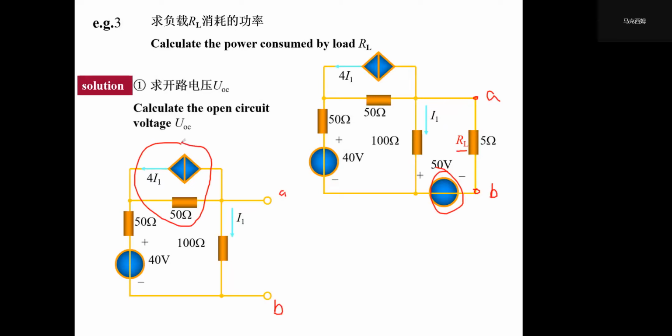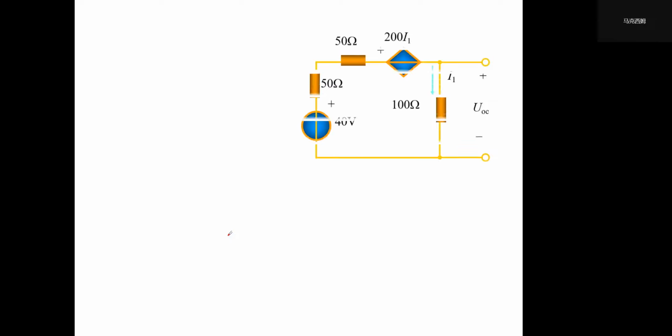We're using the traditional way to transform this parallel connection of the controlled source and its resistor into a series connection. And we leave this control branch in. So we can calculate the corresponding voltage. We can use KVL to calculate that.